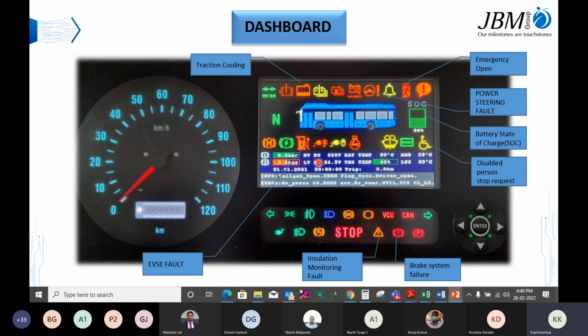So this is the difference from our previous projects as well, and the difference from the existing OEMs as well. All the telltale information which is mandatory, which is required for homologation and which is required for the driver itself, is placed digitally, and some is part of the cluster itself, like the VCU CAN, brake pedal, ABS, and some informatory like whether the front fog lamp is on or not.